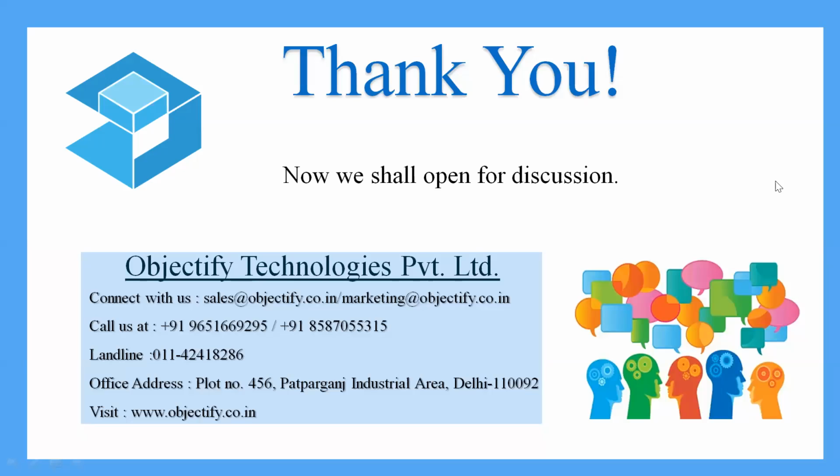As you might know, in the manufacturing industry, you need a certain level of detail of information for machines to automate the movements, the mechanization, in order to do certain operations. In the case of age-old technologies which are very matured, like die casting or forging or any sort of injection molding, you prepare a mold and it does automated movement for pressing and ejection, so that the cavity is tightly bound, you fill in the material in those cavities and then you remove it. So it's a very simple mechanized operation.